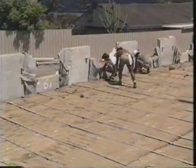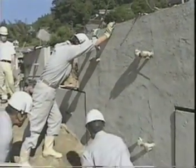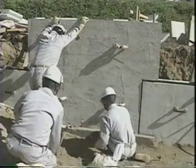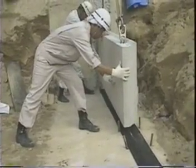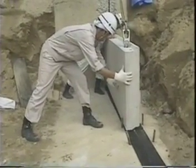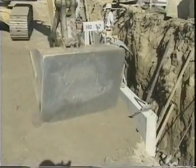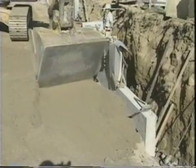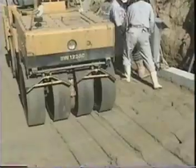Steel reinforcing strips are laid on top of the fill, and one end of each strip is bolted to a facing panel lug. In this similar system, steel loops protrude from the rear of T-shaped panels. First, a base course of facing panels is erected on a small concrete footing, which is cast in situ. Selected fill is placed in layers until it reaches the level of the first pair of precast loops. It is then compacted.